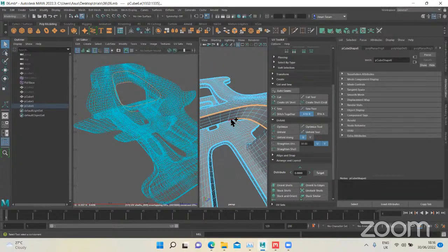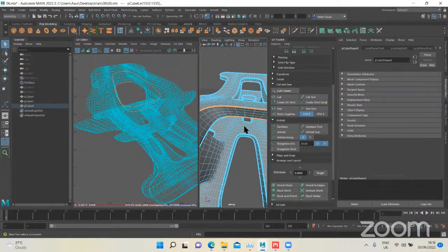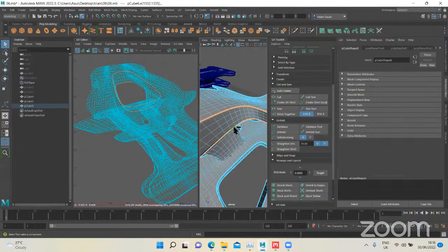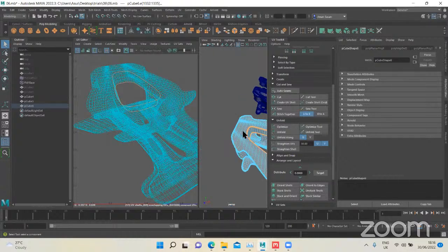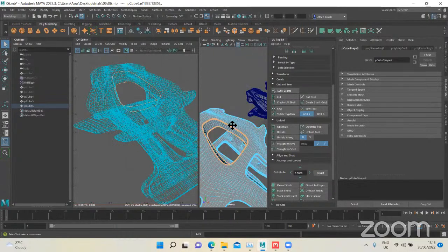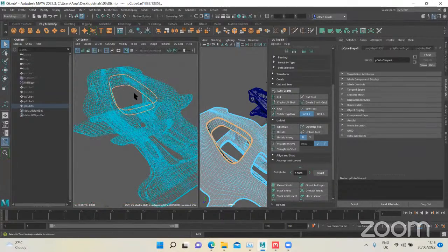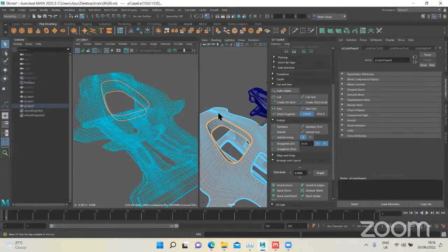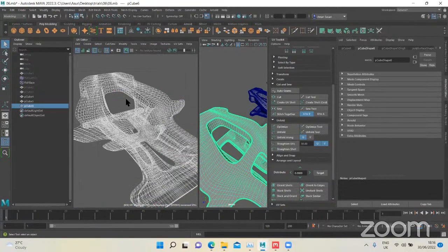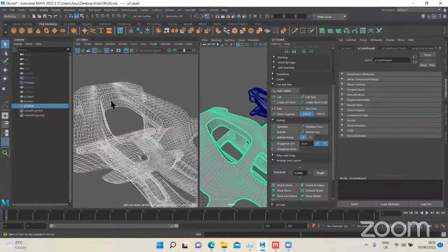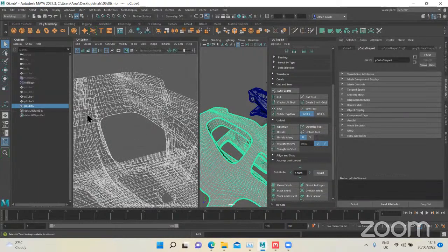Because I have a model of this already UV cut, which I can show you. After I've selected both these edges, I use cut. Now if you go to object mode and select this, it's going to be this ring, but you'll actually see a bit of a thick seam that's made.